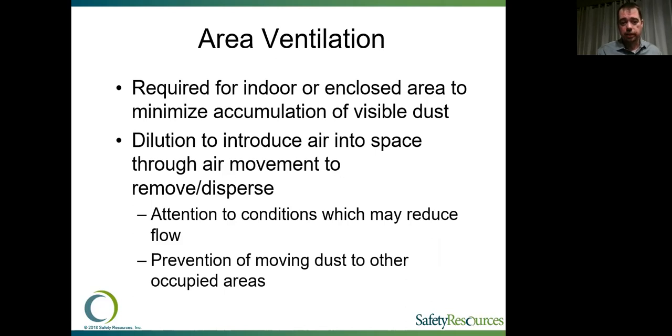I can't have people coming in and closing windows or closing doors, which are going to cut off that flow of air. And then we also have to make sure that we are looking at where we are ventilating air around too. So I can't start performing the work where a lot of dust is being generated and then just put a fan in place and hope to blow that dust somewhere else. That dust is going to go somewhere. I can't blow it into other work areas or where I may have exposure for other employees or other contractors or trades.